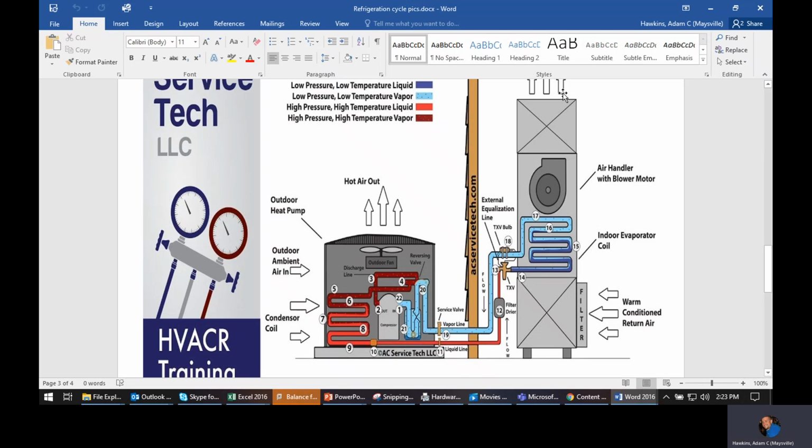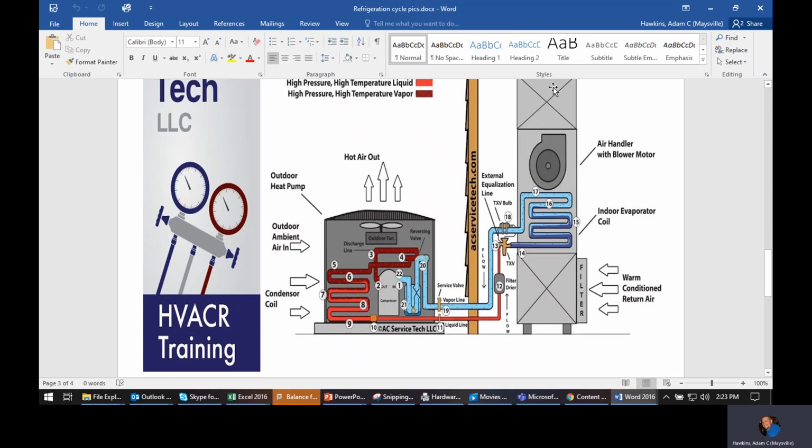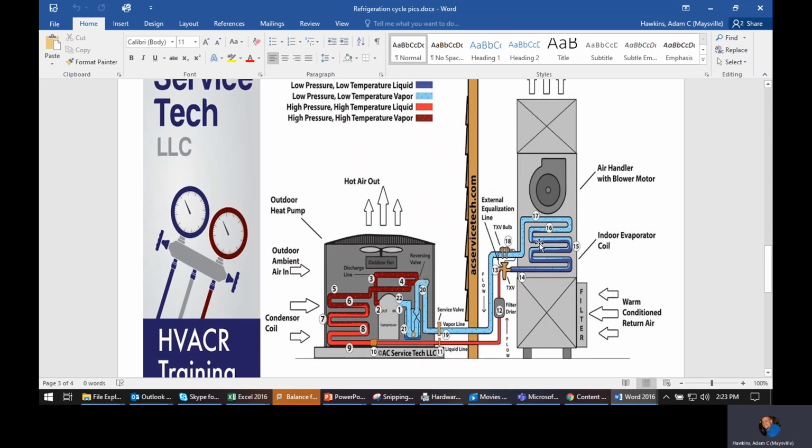And so as a result, the air coming out the top is going to be colder. And that's what we've said in class before: if you want a visualization of how much capacity that cold line of vapor refrigerant actually has, feel the difference between your room temperature and the supply temperature. You've got a 20 degree temperature drop from your whole house, and it's all being captured in this line that seems to be very cold, but it's all because of the latent. So that latent change happens until that completely evaporates. Once it completely evaporates, everything beyond that point is known as superheat.